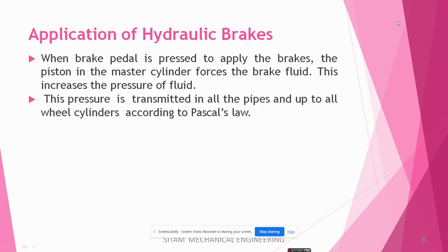Next, applications. We have many applications of the hydraulic brake system. When the brake pedal is pressed to apply the brakes, the piston in the master cylinder forces the brake fluid. This increases the pressure of the fluid. This pressure is transmitted through all the pipes to all the wheel cylinders according to Pascal's law, as we discussed earlier. This increased pressure forces out the two pistons in the wheel cylinder. These two pistons are connected to the brake shoes so that the brake shoes expand out against the brake drums. Due to the friction between brake linings and drums, the wheel slows down and the brakes are applied. In this way the brakes are applied.